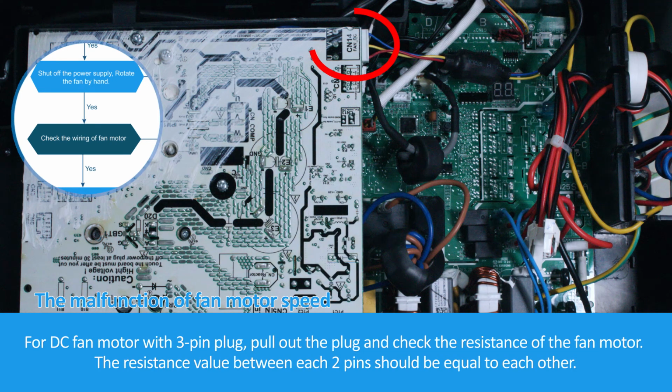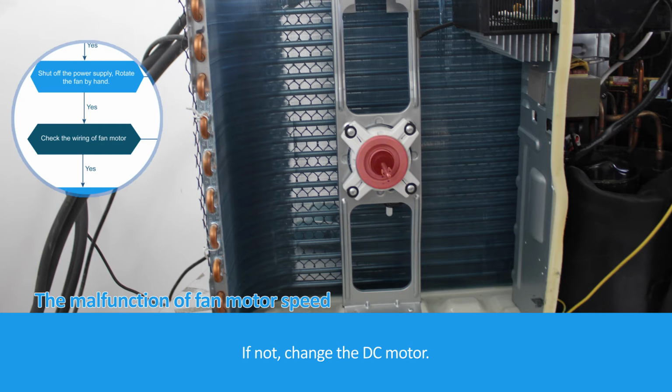For DC fan motor with 3-pin plug, pull out the plug and check the resistance of the fan motor. The resistance value between each 2 pins should be equal to each other. If not, change the DC motor.